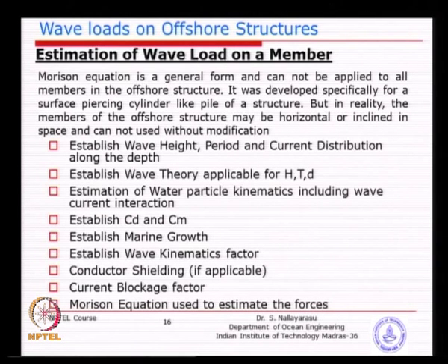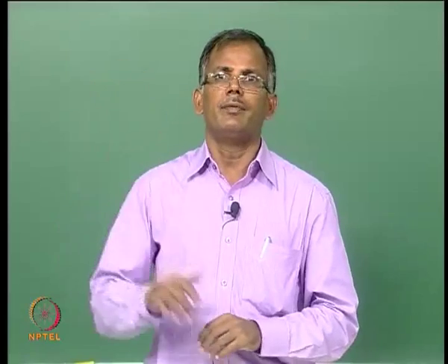Establish marine growth, wave kinematics factor, and conductor shielding, each of which has a certain effect on the wave force calculation. Each one of them will be looked at in detail over the next few classes, and then finally we come back here, apply all that information into the Morison equation, and arrive at the design force. I think we will stop here and look at it tomorrow.